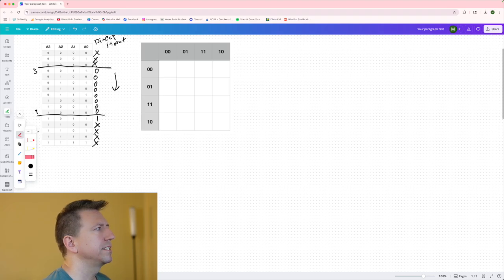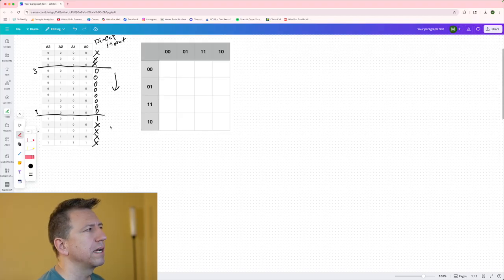Now, if you want to design for instability or for a start state that is not 3 through 9, then you could make these all 1s, and it would be a little bit more complex combinational logic, but that will handle any sort of accidental movement out of the state that we want it to and reset the counter at that point. Okay, so let's build this truth table then.